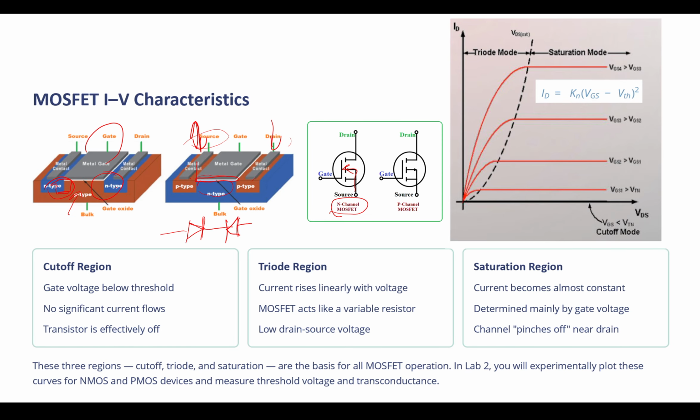so we cannot use what we used before in the diode to push the charges, or affect the behavior of those two diodes on the other side of the transistor, in the source and drain. But what we can do is that we have a gate near that channel. We can apply an electrical field.